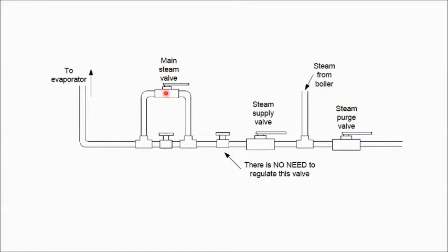When opening this valve, start the stopwatch timing. When the first bubble appears, time taken will be recorded, and the reading of the steam flow rate and pressure will be recorded. After 20 minutes, close the steam supply valve and open the steam purge valve at the same time. No need to close the main steam valve because the main steam valve will obtain the steam flow rate and pressure for the next running.